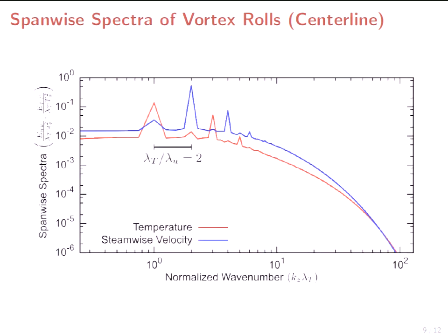And so in effect, you have an inertial range turbulence over here interacting with the discrete large-scale instabilities of the larger-scale flow. And so we want to be able to clarify some of these interactions and to see how this affects, say, maybe the synoptic scale pressure gradients that actually are what drives the mean energy into this flow, and how they cascade down.